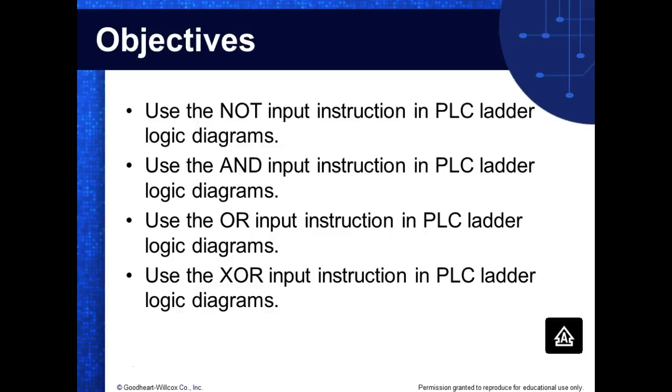When we do logic, most of the time we're dealing with 2 things. So if I was going to do an exclusive OR, I'm going to do it on what we call contact A and B. It is still an exclusive OR with A and B. So what I can do with these logic instructions is exclusive OR 16 bits with 16 bits.